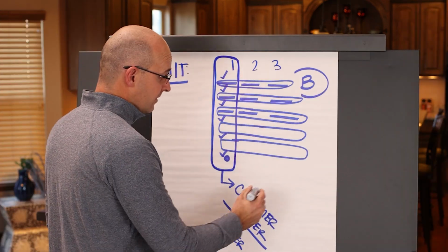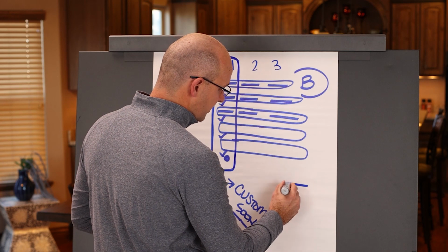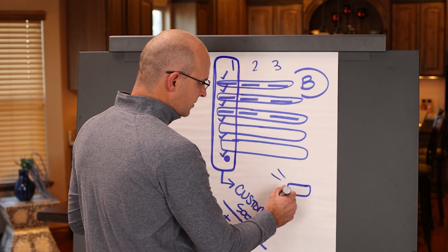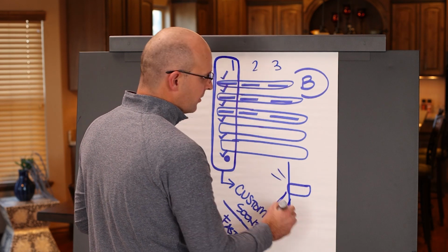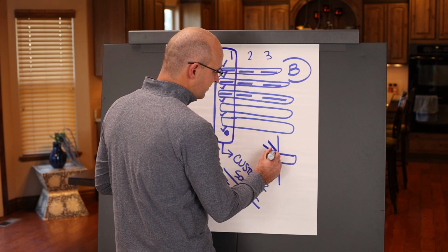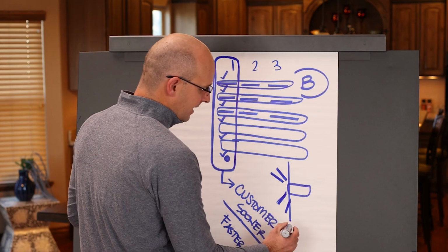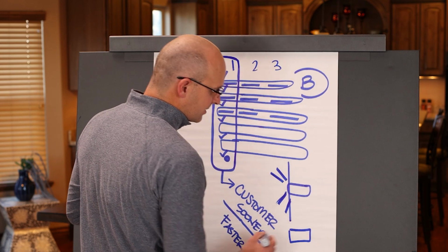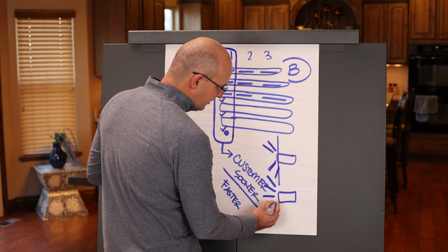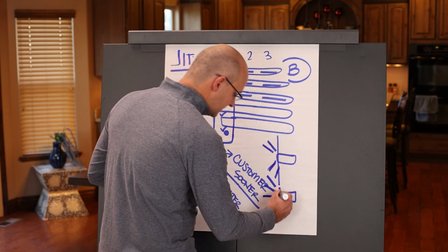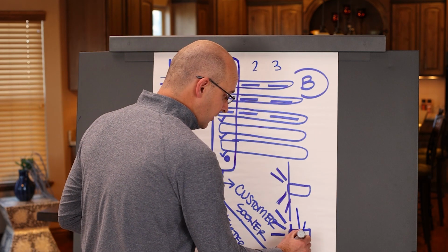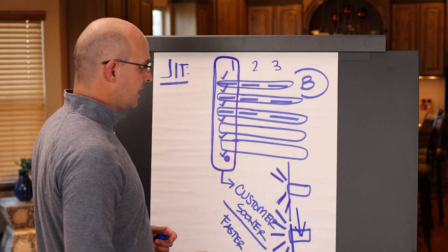Okay? The other thing is, if we're looking at this activity, this submittal process, we know that any other ancillary support resources or equipment should be here ready for that submittal review just in time to enable that activity. So let's say that activity wasn't a submittal review, but was actually a construction activity. We want the materials, the information, the labor, the equipment, and the layout just in time so that it can flow and so that we can focus on that flow, not too soon, not too late, but in a flow.